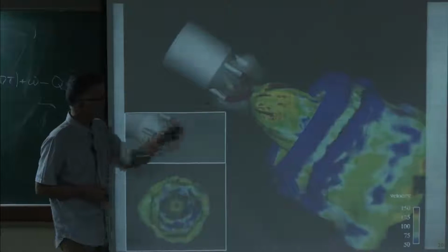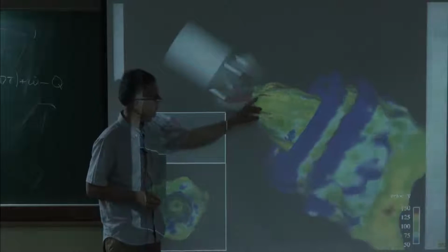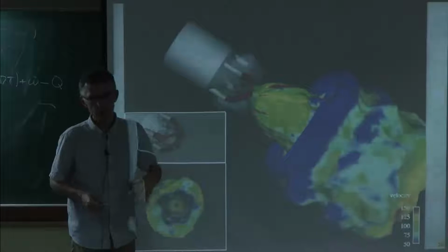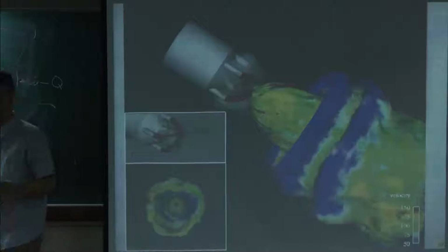Same thing here for the case with pilot flames. You can see the pilot flames here. You see these pilot flames actually are very long. It takes a long time to mix, and the flame is stabilized here. So in that case, in this zone here, you have a diffusion flame, and you must be able to account for it.